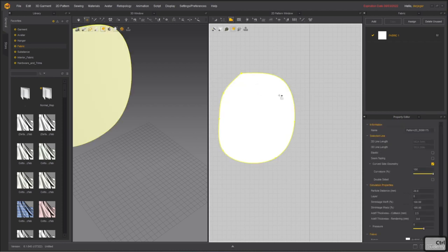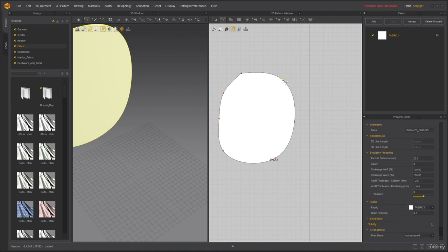Sometimes for certain things I prefer the handles, and for other things I prefer this one, especially because sometimes you're going to go into the edit curve point, and when you have the handles, it becomes a little difficult to manage. In this case, it's just easier. You move the point where you want, and the curve is going to behave closer to what you expect.